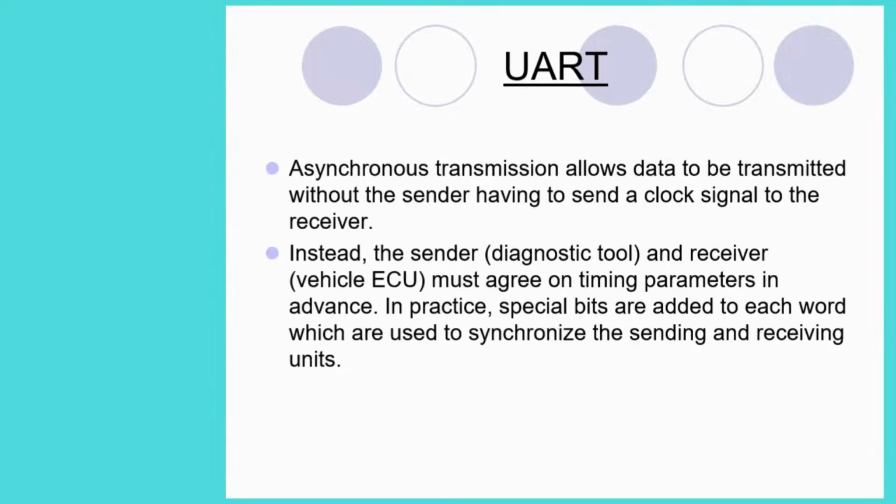Asynchronous transmission allows data to be transmitted without the sender having to send a clock signal to the receiver. Instead, the sender, the diagnostic tool, and the receiver, the vehicle ECU, must agree on timing parameters in advance. In practice, special bits are added to each word which are used to synchronize the sending and receiving units.